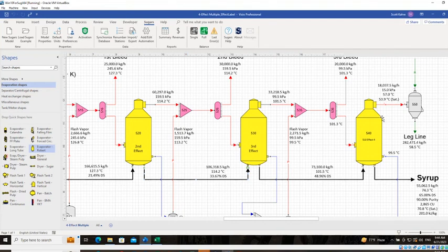Essentially, that's a mechanical design calculation, and Sugars being a mass and energy balance software doesn't really get into mechanical design of equipment. So we leave that to the evaporator designers to determine the exact heat transfer coefficient that they predict for new equipment.